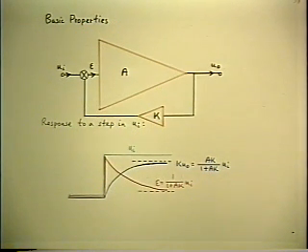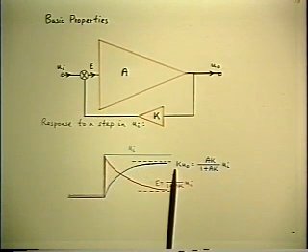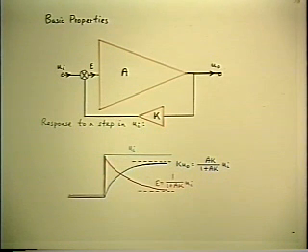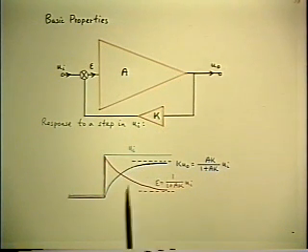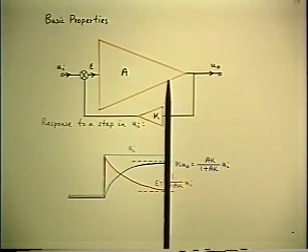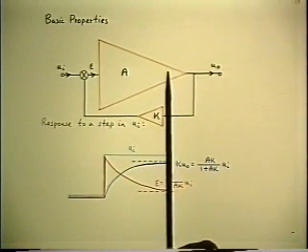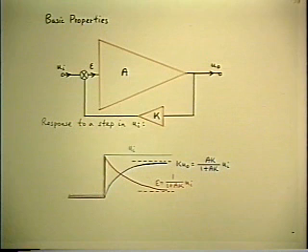One thing is for certain about it, it'll take a lot longer to reach the final steady state than if the system had remained linear. So that's something to watch out for, especially with modern ICs that have all this gain. That's very nice to have all the gain, but it's also very easy to overload them.